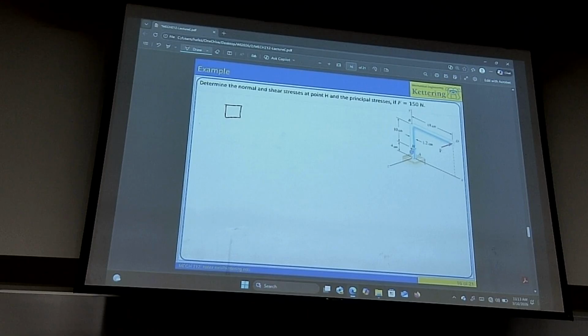So we want to enumerate the facts. Drew, okay, I think it's your turn. This force F, let's enumerate the effects of it. Are you actually loading or pulling or pushing on H if you load it like this? No, then no axial effect, no F over A. All right, well done. And then, are you causing any torsion? Are you twisting it in any way? Well, it would be causing some form of shear stress moving across the surface. Very good. And the equation for shear stress?